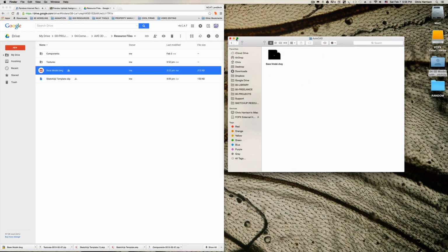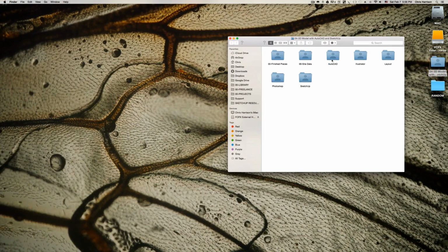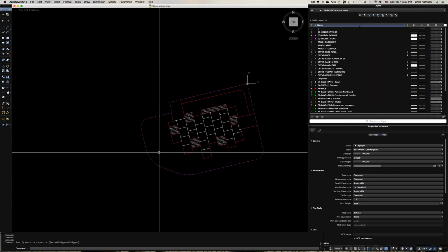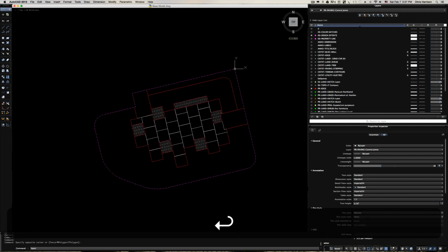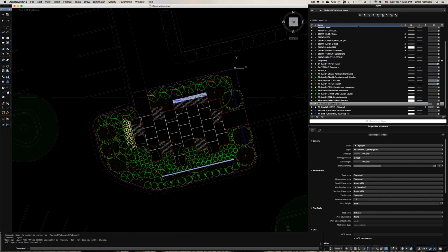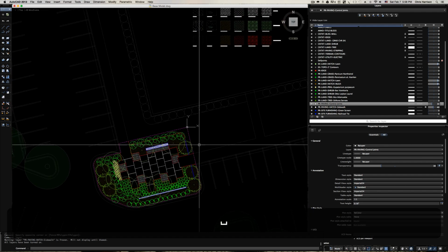We have all our stuff situated where it needs to be, and we'll start working from our established folder. So I'm going to minimize that for now. I'm going to the folder that we created. I'm going to the AutoCAD and open the base model DWG up. Alright, so now you have the file open. You'll see that the edges layers are on, but I'm just going to turn everything on so you can see it. So it's a completed model. All the plant materials are blocks. I've actually created a separate layer for each plant material to make it easier to render in Photoshop, and also to help better organize the file when we get into SketchUp. Same model we have been working on though.